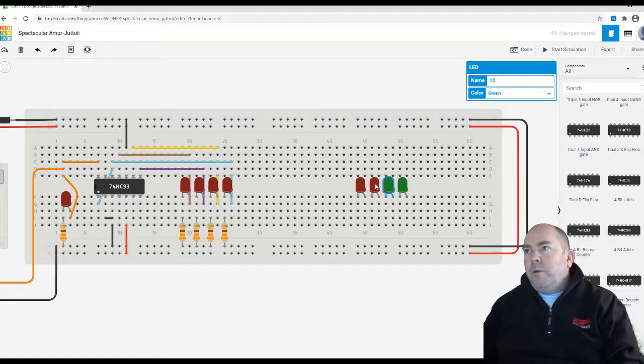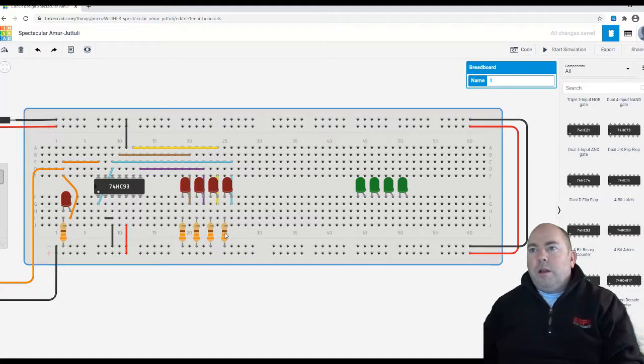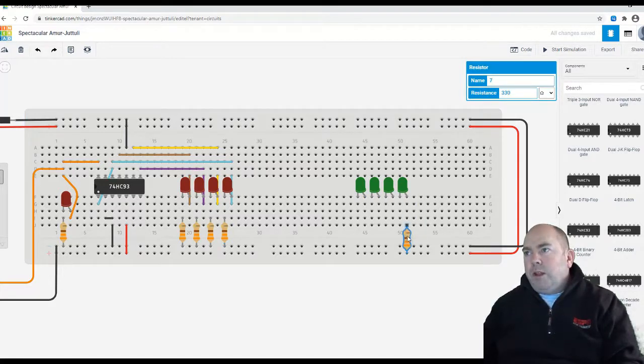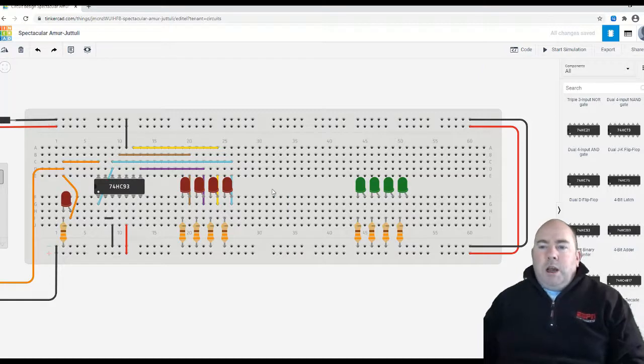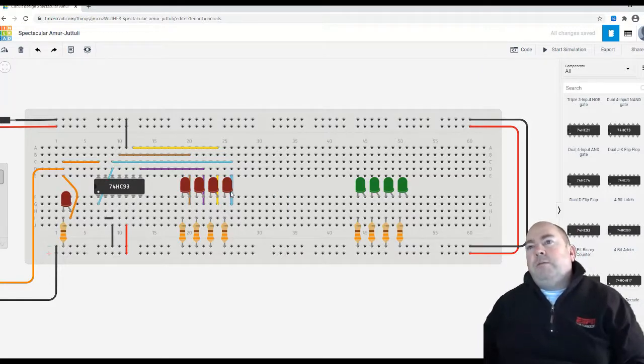These are going to be our 1s counters over here, and then we're going to have the 10s over here. We're going to count in 1s, and every time we hit 9, we're going to add another to our 10s count and reset the 1s count. You can see how it goes to 15 now, so we actually want it to stop when it hits 10. Add another one over here, and reset over here, and then keep on counting 0 through 9 here, and then increment up to 0 through 5 over here. Once we hit 6, or 60, we'll reset ourselves back to 0.